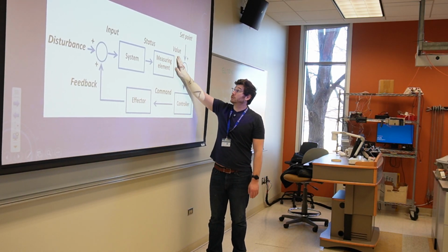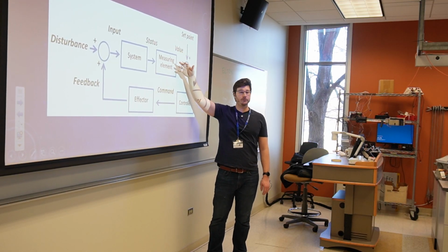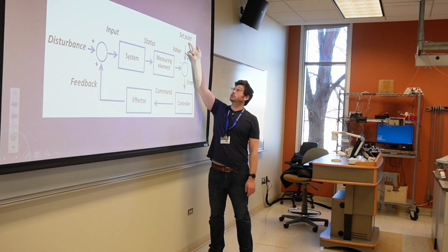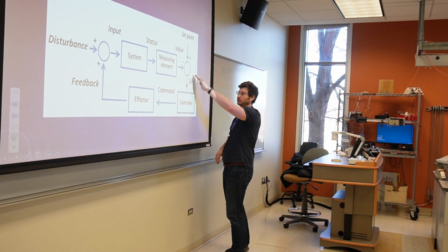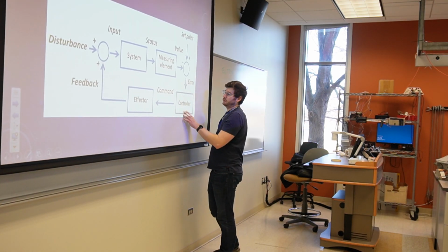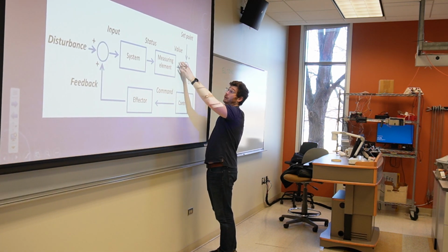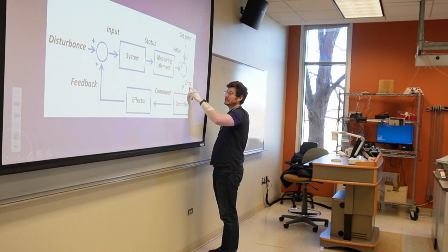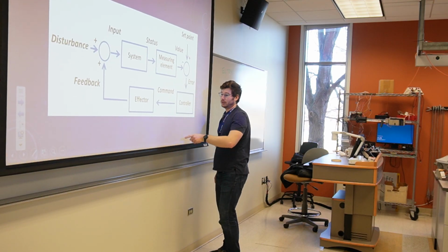We have a value, which is the speed that we're currently traveling at, say it's 48.5 miles an hour, so 1.5 different. And then we have the error. That's the difference between the set point and our value, the 1.5 metric, right? We are faster or slower by some amount. We're off by a little bit. That gets all fed into our controller. That's the computer living inside your car that gets this error. Pretty much all it really cares to see is the amount of error, the difference between where it is and where it wants to be.